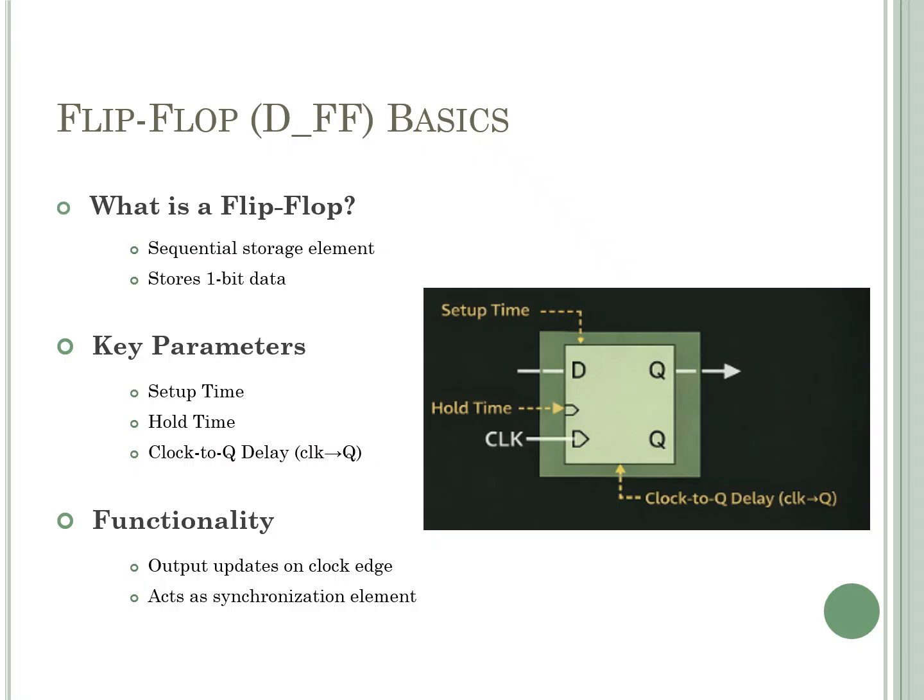So the flip-flop defines the start and end of data movement. Flip-flops store data, control timing and synchronize the entire circuit. In real chip design, most timing issues are actually related to flip-flops, like setup violation and hold violation. So understanding flip-flops is extremely important.